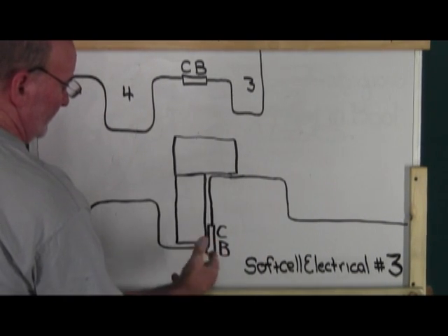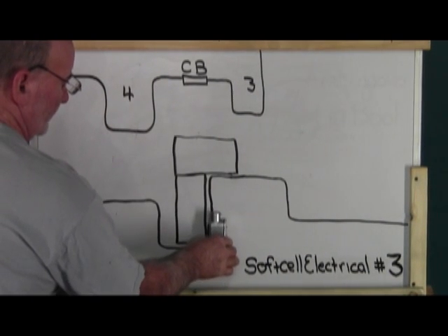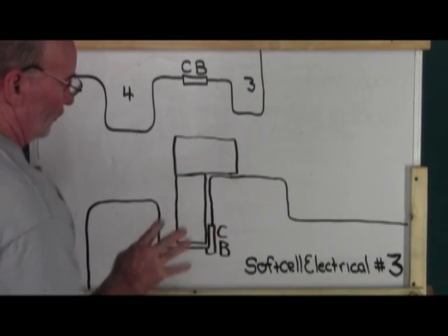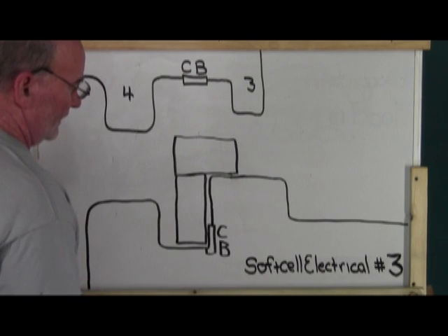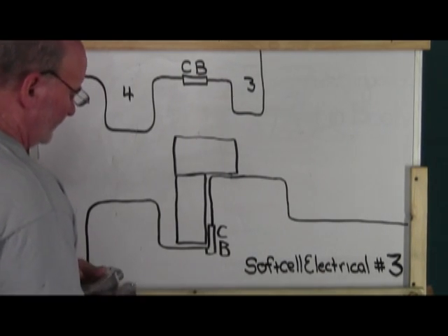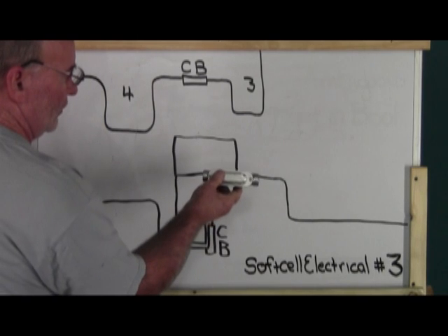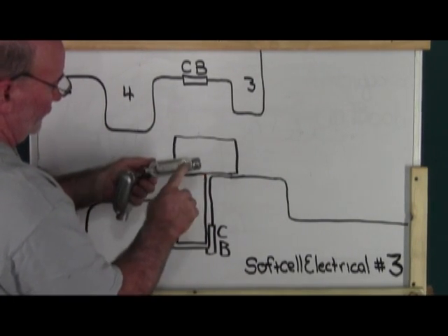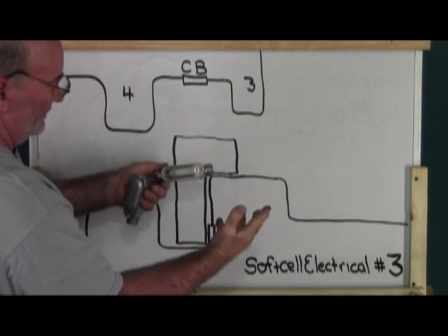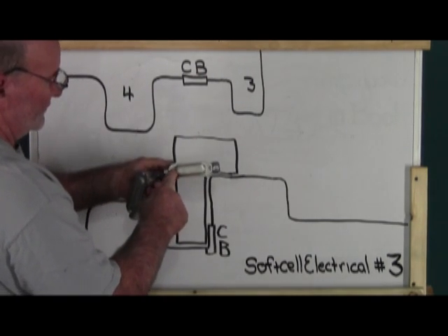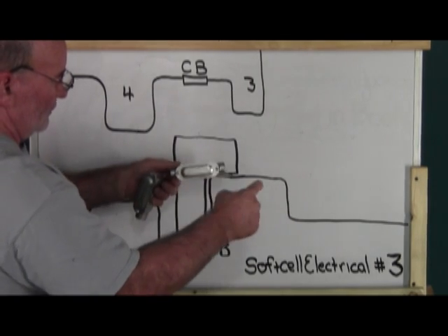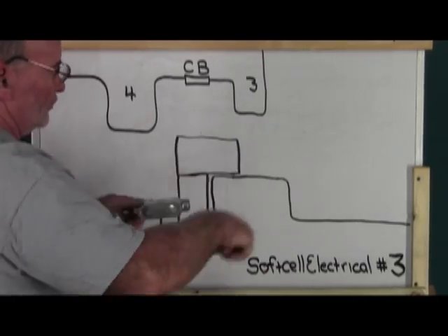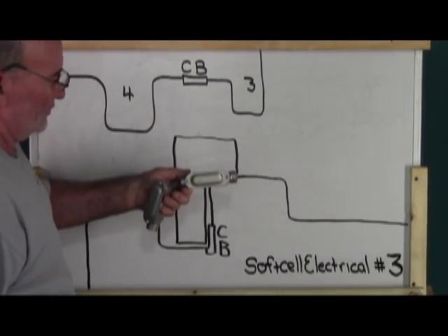So you can have 6 bends, and if you have a conduit body in between, then you're still within the 4 bend rule. They come in very handy indeed. These are also good for extremely long runs where perhaps you have a 150-foot run or maybe a 300-foot run. You might want to put these in between, so at 150 feet you can pull out a loop, put in the fish tape, and re-pull, and basically loop around so that your pull is much easier.